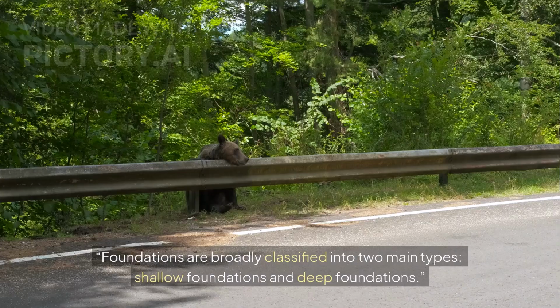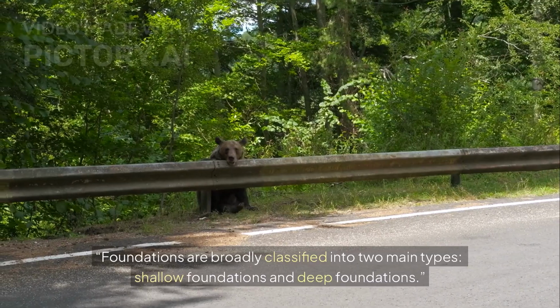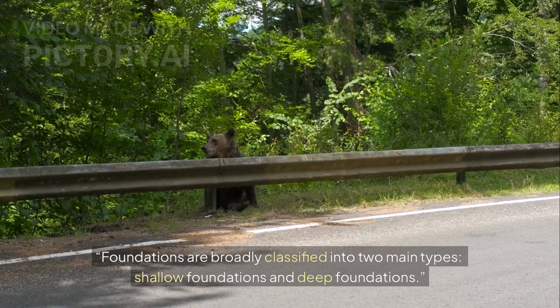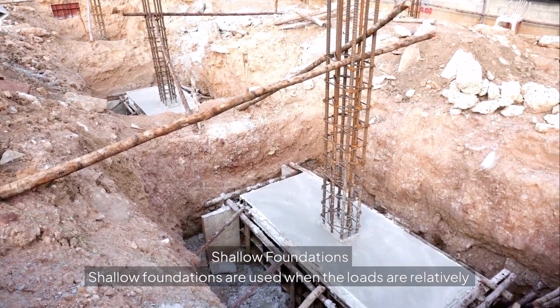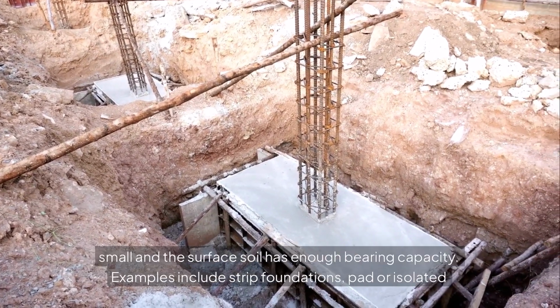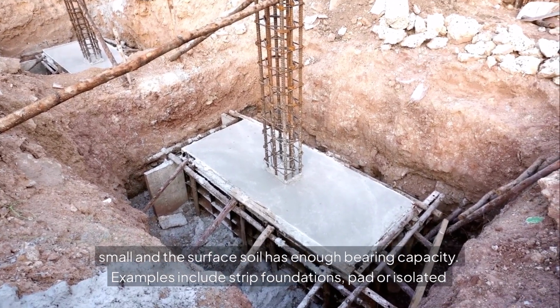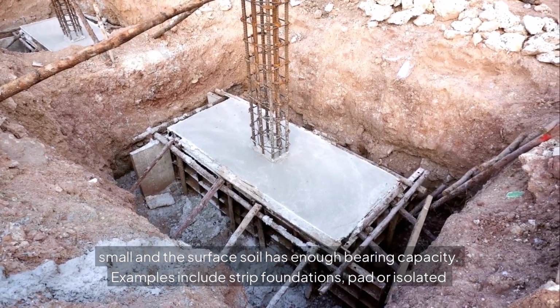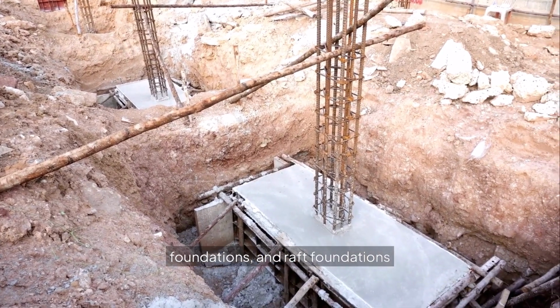Types of foundations. Foundations are broadly classified into two main types: shallow foundations and deep foundations. Shallow foundations are used when the loads are relatively small and the surface soil has enough bearing capacity. Examples include strip foundations, pad or isolated foundations, and raft foundations.